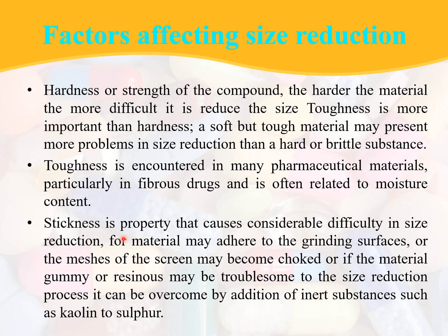Next, stickiness is a property that causes considerable difficulty in size reduction, because the material may adhere to the grinding surfaces or meshes of the screen and may become choked. If the material is gummy or resinous, it may be troublesome to the size reduction process. It can be overcome by addition of inert materials such as kaolin or sulfur.